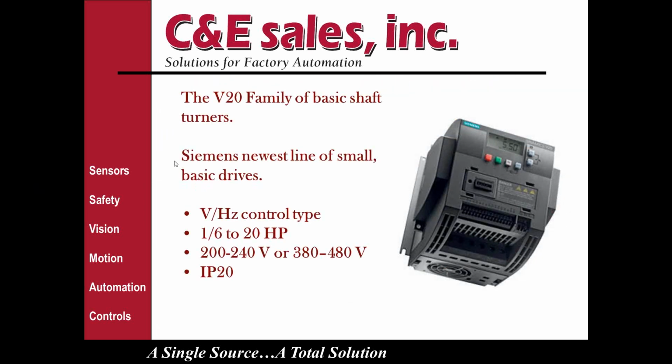The V20 is a new family just introduced this year. We're very excited about some of the capabilities of it. It's a great product for basic shaft turners, for standalone applications. It is designed specifically for the smaller range of products. As you can see, 6 horsepower up to 20 horsepower. It's available in 200 and 380 to 480 volt range. IP20 is the category, so it does need to be mounted inside an enclosure in most applications. And it is limited to volts hertz mode.